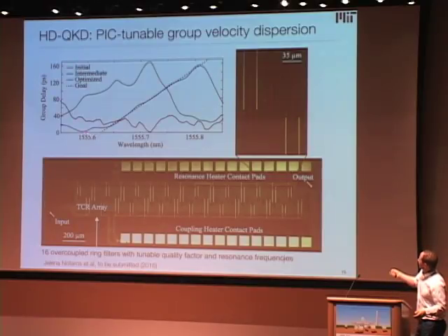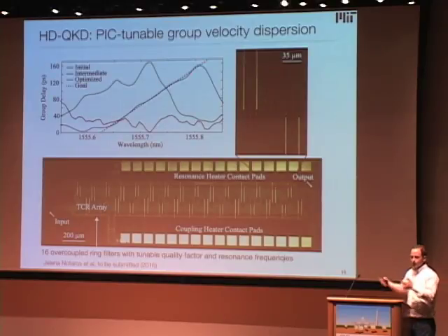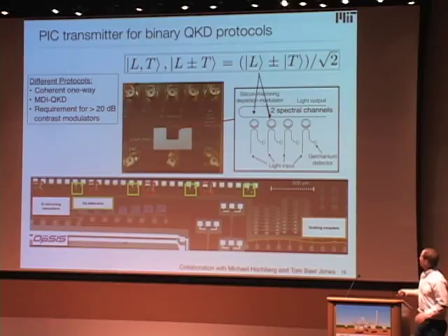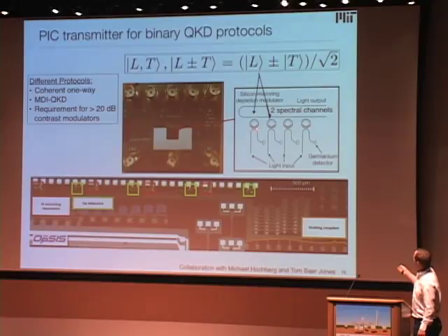And so, for example, here is a group delay that we can just program in. When the devices first turn on, the group delay is random. Suppose we want to have a linear group delay for group velocity dispersion, and we can just program that, and that's the experimentally measured curve here in blue. So now you can have Alice have normal group velocity dispersion, and Bob have anomalous group velocity dispersion for their measurements.